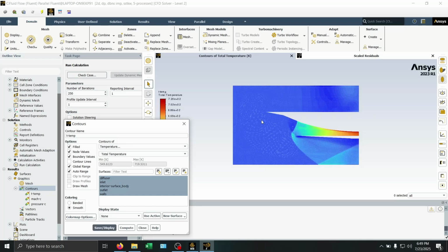So we see the total temperature stays fairly constant through the oblique shocks, and then it does have a bit of an increase after the last shock. All right, so shocks are expected to be adiabatic, so it shouldn't change much between shocks, but we do have an increase throughout this range. Now there is viscosity, so of course it's not isentropic flow. There are going to be losses and friction, so it will change slightly, even though the math says it will be constant, just because of those losses.